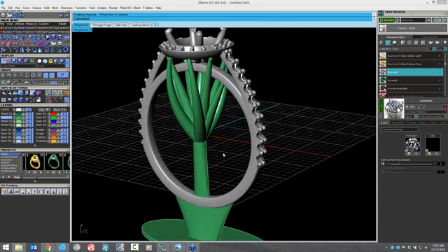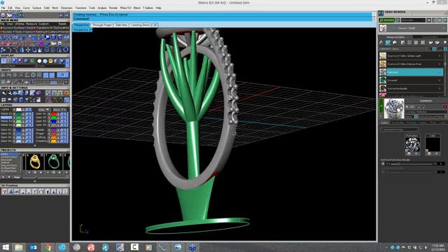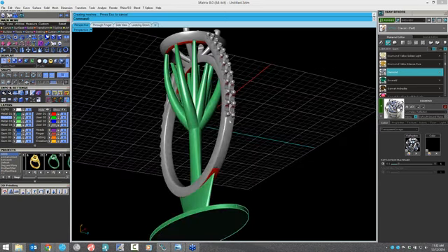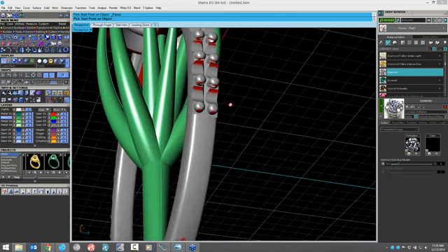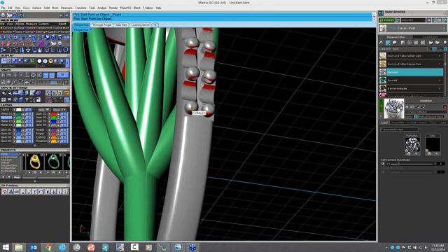part of the ring. The last part that I need to worry about here is the downward facing prongs. Okay, so to do that, we have this blend support with quad mirror tool, and there's different options in here. This is the one I'm going to use for this section. So we come up here, and on one of the downward facing prongs, I'm just going to click on the mesh, and then as you move off it, it starts a little support.